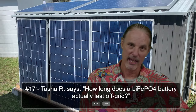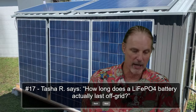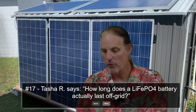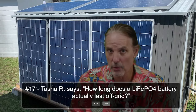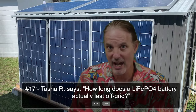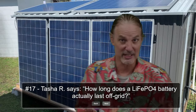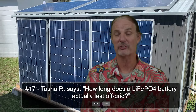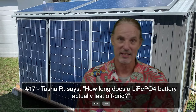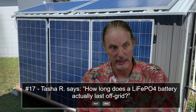In other words, if you are going to discharge your battery all the way down to 0 and you charge it all the way back up and it stops at 90% and only resets to 100% because it hit the high voltage, you recognize, or I hope you would recognize, that 10% of your battery is missing. And if 10% of your battery is missing and you call it 100%, then your battery will die at 10% and your state of charge will be wrong again.